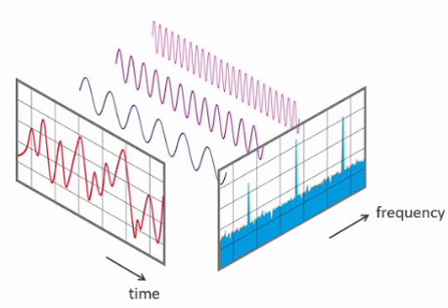Relation between Laplace transform and Fourier transform: F of sigma plus j omega equals the integration from minus infinity to infinity of f of t e power minus sigma t e power minus j omega t dt, which equals the Fourier transform of f of t e power minus sigma t, where s equals sigma plus j omega. At sigma equal to 0, s equals j omega, and the Laplace transform becomes equal to the Fourier transform. The Laplace transform calculated on the j omega axis is the Fourier transform. Fourier transform is used for signal analysis and Laplace transform is used for designing the system.